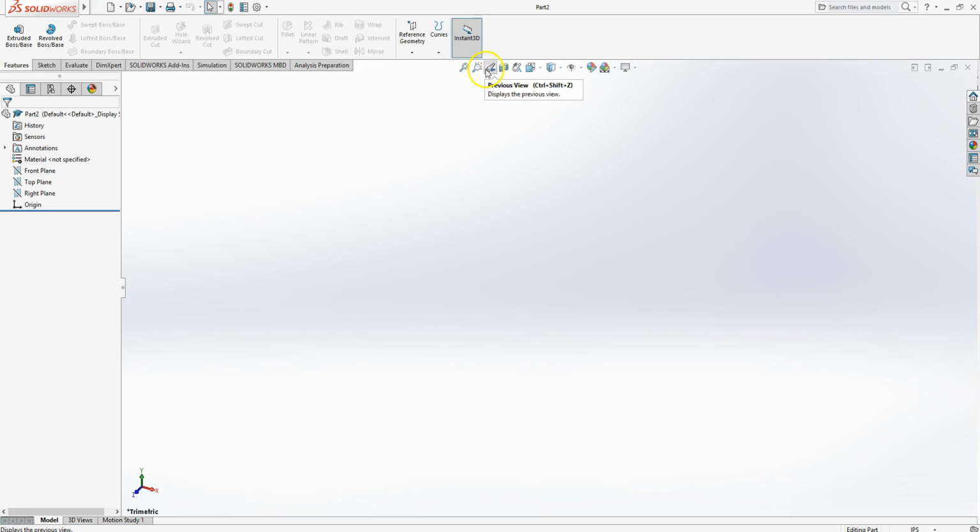So if you wanted to look at something a certain way, you can use this toolbar. You have your sketching tools if you click on this. So let me just go back. This on top will be referred to as the ribbon. The ribbon changes as you select different tabs. So when I say look at the ribbon, you're looking on the top part. When I say tabs, look at these tabs. Okay.